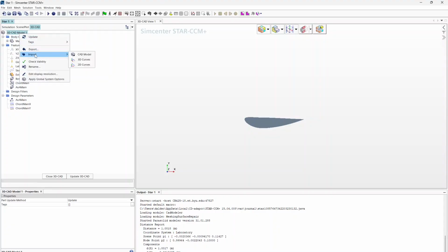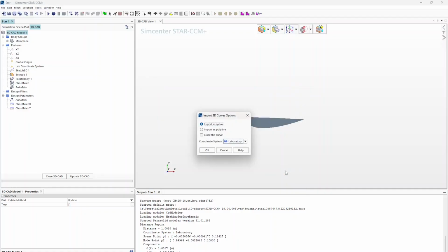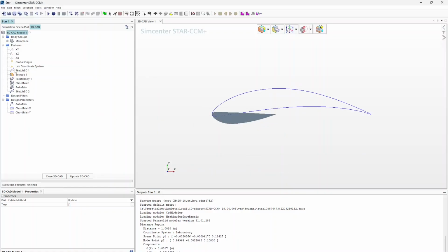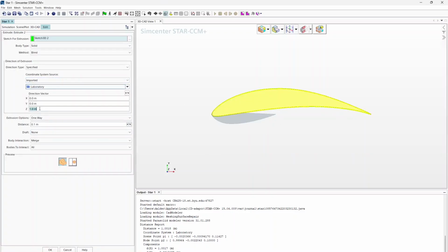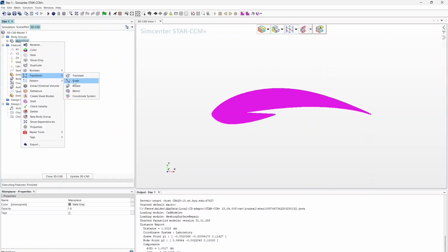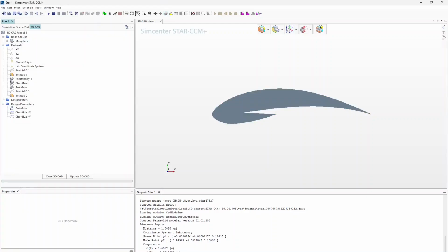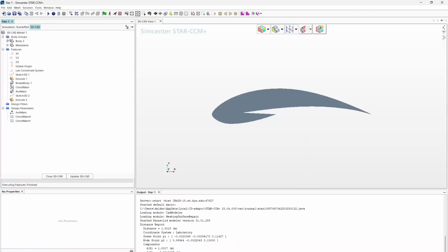So we, again, are going to import a 3D curve. And let's pick the CH10 for our flaps. Same as before. Now we're going to extrude this again. So right click, extrude. Again, -1. Okay. I'm going to try to go through this as fast as I can so we don't bore you guys. I'm going to again transform scale. Oh, sorry, forgot to rotate first. Oh, I made a mistake. Let's go in and edit. So it did try to merge these two airfoils together because they were touching. So I just unmerged it, and hopefully now we have a second body.